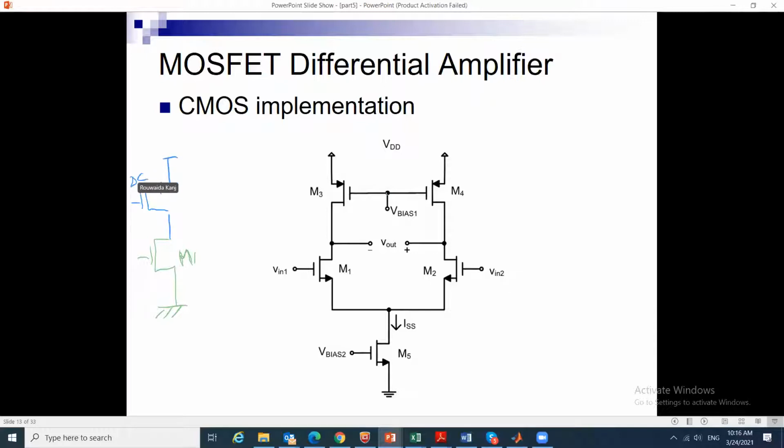And this is DC. So what happens to this transistor? This is my V in, and this is my V out. I can really replace it with its effective resistance, right? It's as if I have here RO3. Okay, this is the half circuit. With the same here, it's as if I have on this side, really instead of all of this, RO4. I'm just using transistors to create RO3 and RO4.